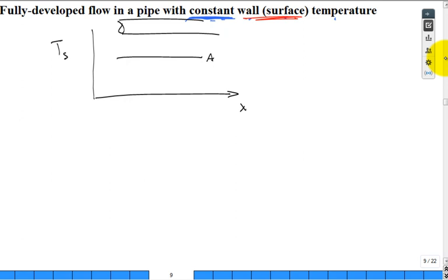No problem. Okay, now let's do this. I want to talk about the temperature of the fluid, the mean temperature, the single mixed or bulk temperature is what they call it, a mixing cup temperature. It's that mean temperature. It's a flow rate average temperature. All right. As it goes down the pipe right here, let's say it comes in at this value, and the T_s, it's a hot wall, so T_s is greater than T_m coming in. It's a hot wall. All right.